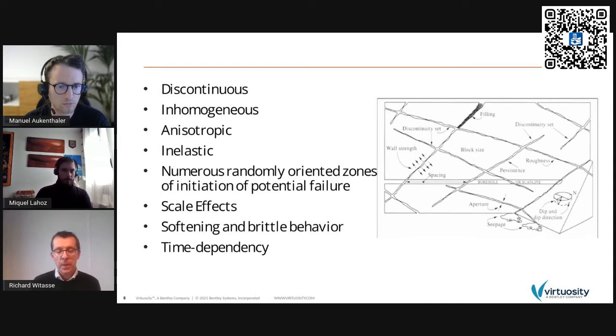That is one aspect. By time dependency, we can also think about swelling, which is also characteristic of rock. The fact that the rock, with time, starts developing swelling strain, the amplitude of which depends not only upon time, but also about the level of confinement, stress level being applied. Correct. So this is briefly presented what this would mean from a numerical modeling point of view.